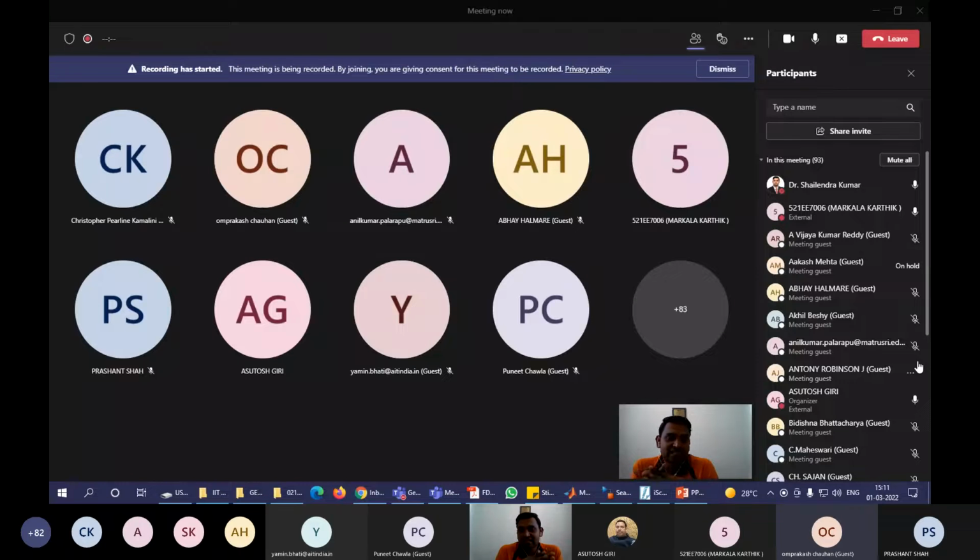As I discussed, in case of single stage there is no decoupling unit, so we have to go for higher voltage. Number of series, one or two panels you can increase in series. There are series panels and parallel modules. So in series, instead of taking 23 panels for 400 volt or 700 volt for a two-stage system, you can take 25 panels for a single stage system.